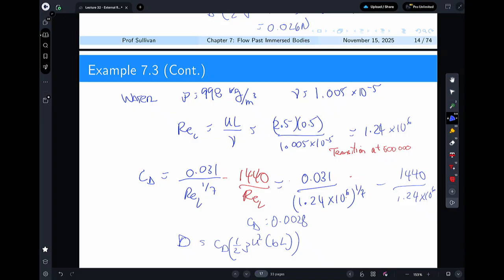Oh, this right here, 0.03? Yeah, that's from the turbulent relation. So this is, again, empirical. One of the problems with this chapter is that there's not a lot of derivation. You're going to be using a lot of empirical relationships, especially for the turbulence. For the laminar one, you have this 5 that comes out of the basic equations of motion. You solve for it and get that right out of it. But this one is more experimentally based.